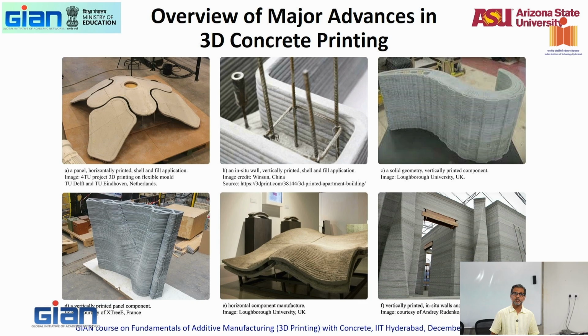4,000 psi concrete, 4,000 psi is what? Close to 30 megapascal, 28 megapascals or so. It will carry a lot of load, and for walls, 28 megapascal is huge, right? 15, 20 megapascal is more than sufficient for walls. But we had to do that for code. So that was your initial way in which you reinforced. Reinforcing still is a big unanswered question. We'll spend some time on the last day talking about some challenges. No real solutions, but some potential ways to take care of that.